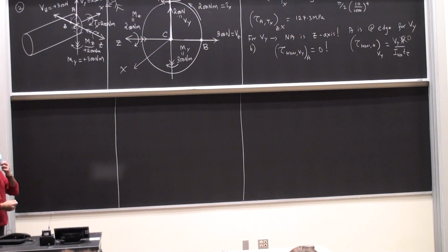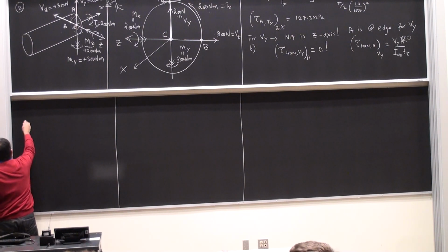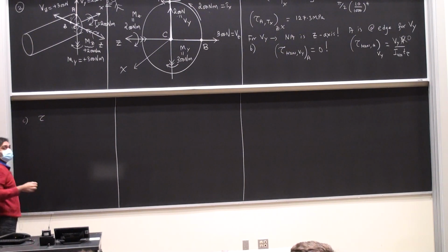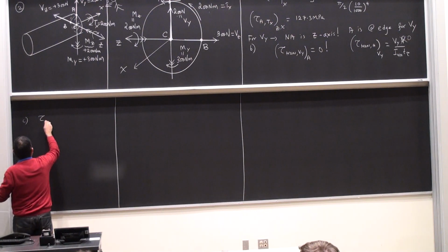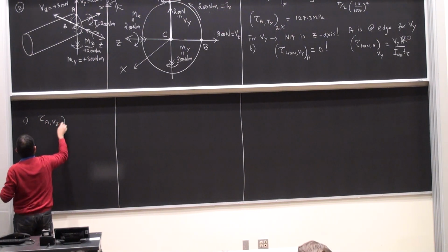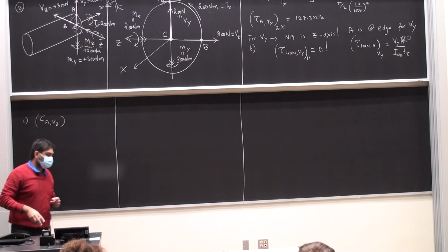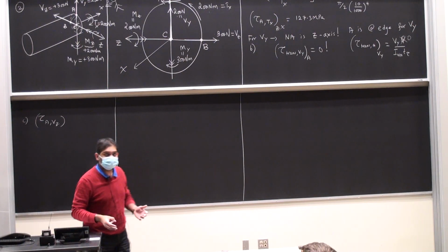Alright, so here is what I have. Vz is what I need to take a look at. So the shear stress at the point A due to Vz, write the formula VQ by It.